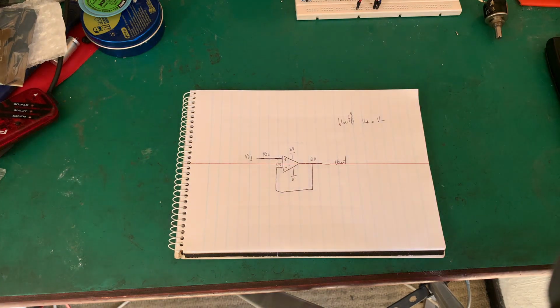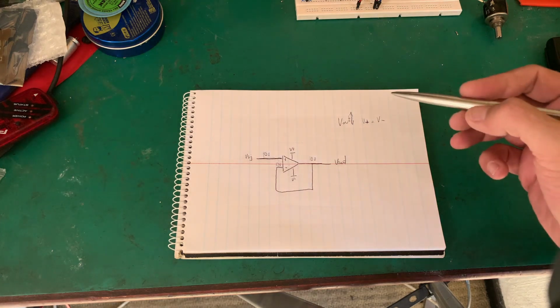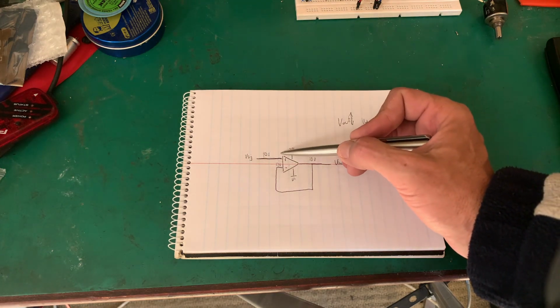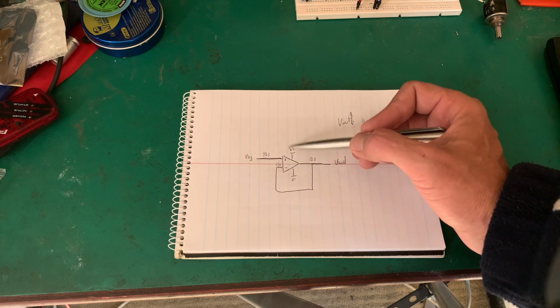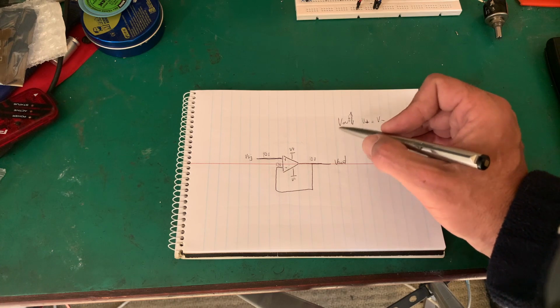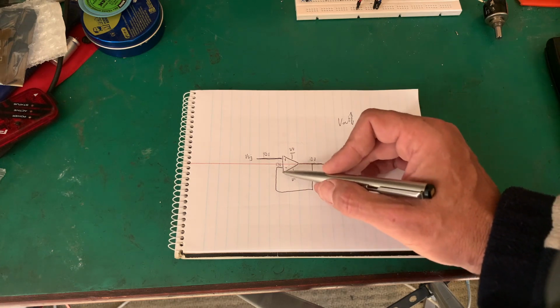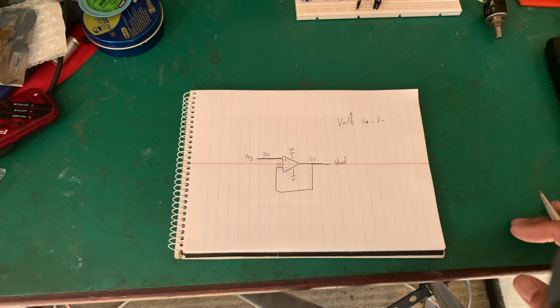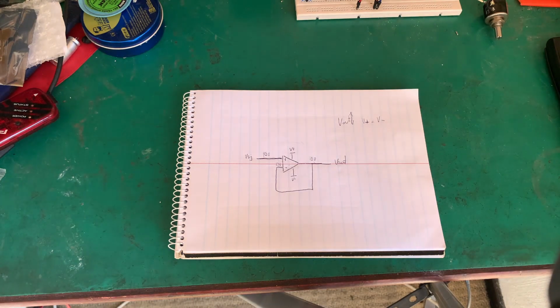So that is one of our first applications of the op-amp. We've said the input impedance is infinite, the output impedance is low or negligible, 0. The output will do whatever it can to make these two inputs the same. With those few rules, we can analyze almost any op-amp circuit, or very simply we can have a look at it and know what it's doing and analyze it relatively well. Let's have another look at another use of an op-amp.